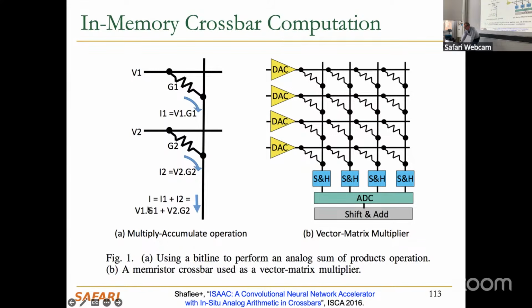And I1, that's flowing through this resistor, is represented as V over R. That's basic law of physics, right? Voltage over the resistance is current. In this case, G is 1 over resistance, so it's resistance to the -1. They call it conductance. So I1 over here is V1 times G1. G1 is the 1 over resistance value over here. V1 is the voltage that you apply over here.